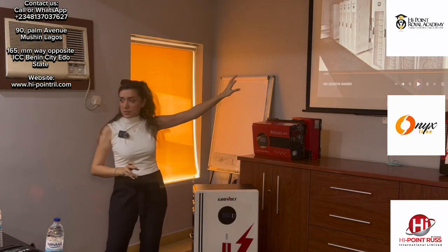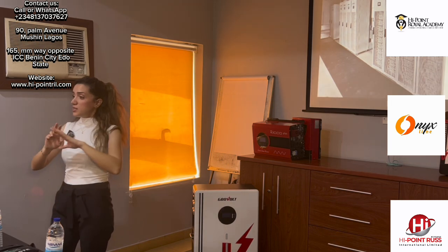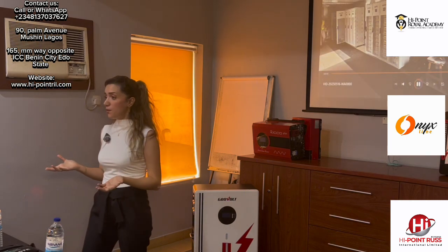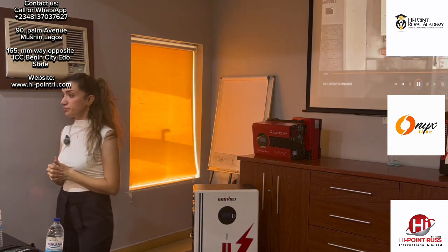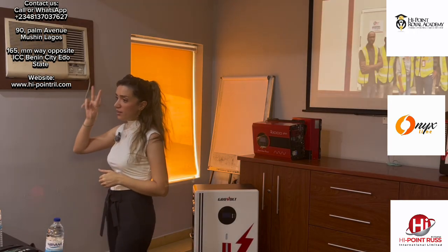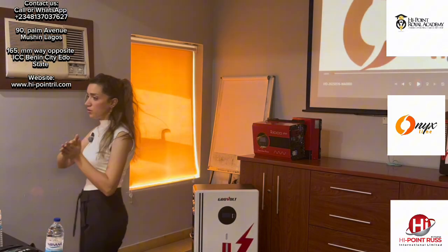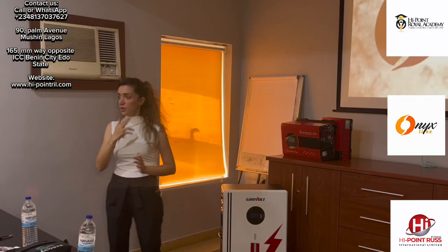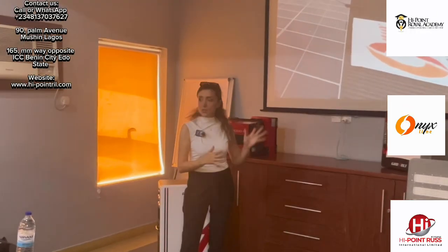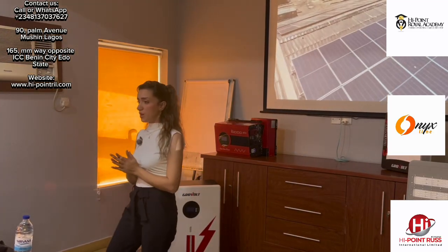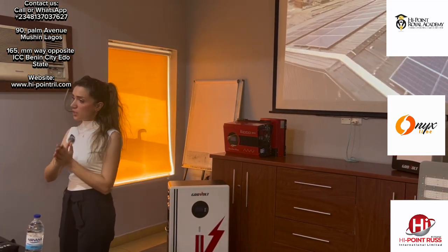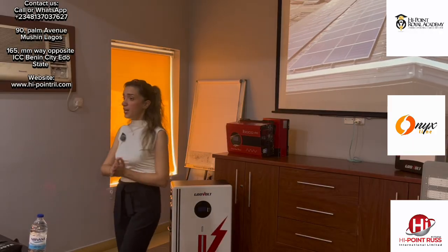This project, for example, the total battery backup is 600 kilo. Each 200 connects to an inverter. 200 to inverter, 200 to inverter. The inverter is 50 kilo high voltage source. The total load is 150 kilowatt hour. Also, the warranty on high voltage battery is 5 years. Solis 50 kilo inverter is available in Nigeria. This battery is also available in Nigeria.